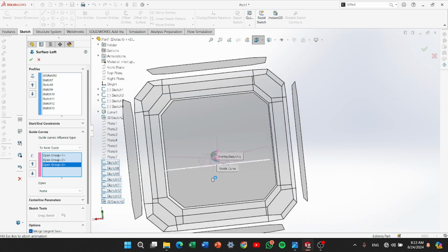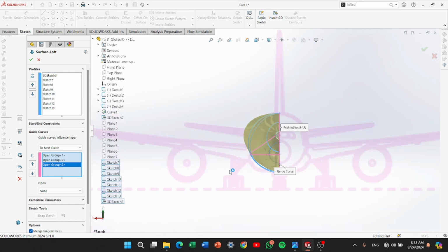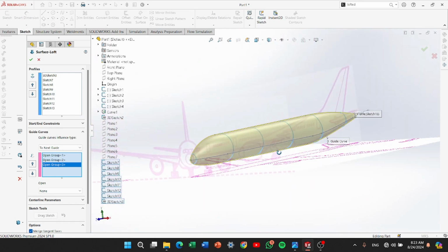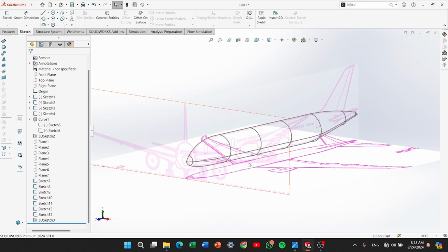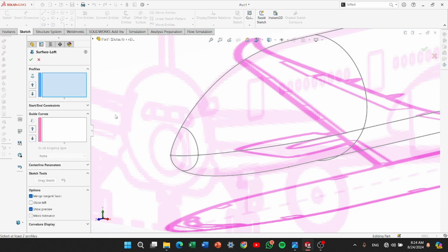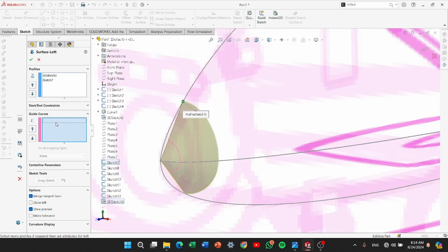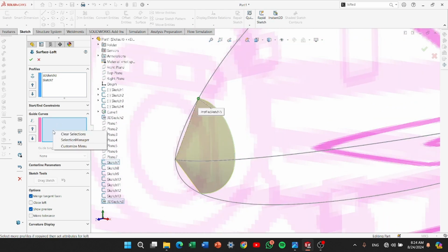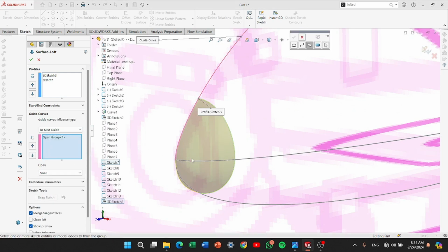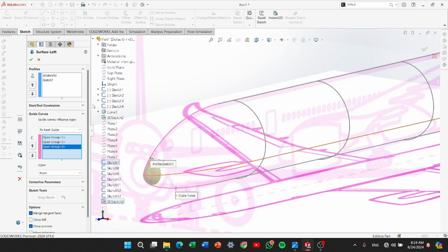But you can see the loft is already out of control and it is kind of bulging out back here. So we need to do it separately. So I just close it and do it separately. Choose lofted surface, only the 3D sketch first. Now the first frame. Okay. Selection manager. This, again selection manager. This, selection manager. The bottom spline. Okay. This is lofted surface one.